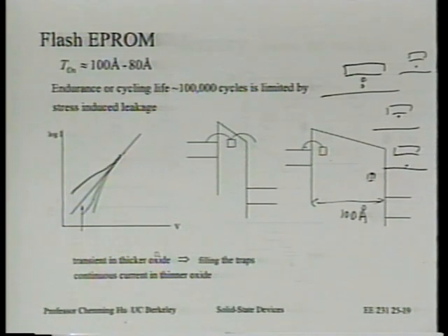How do you test for it? How do you test reliability? Can you afford to actually test every transistor 100,000 times? The answer is no. The time just takes too long. I already told you it takes 1 millisecond, 10 milliseconds to erase. Just imagine erasing it this many times; it will take way too long. So you cannot test it. So what do you do? It's very difficult to do that.